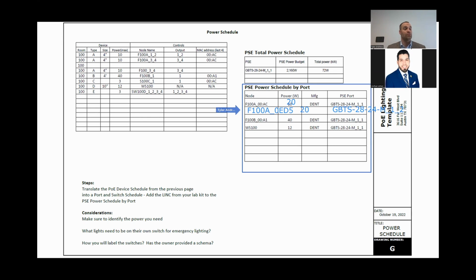You would need to figure 20 because you have 2 of these on one link. So 2 10-watt fixtures on one link would give you 20. Okay, one going this way, one going that. Yep. So if I had 2 of these, let's say I'm holding 2, this one is 10 and this one is 10. This can get up to 10, this can get up to 10. They're all on the same link. So they're helping us calculate our total power budget.